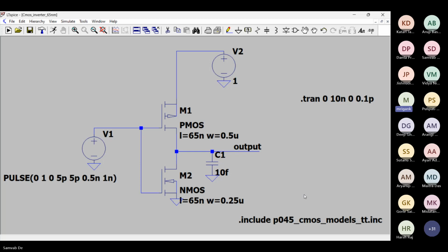All this pole zero analysis that we do, that is for analog circuits and analog signals, because they are small signal parameters, and the small signal resistance, small signal capacitances, they determine the pole. In this case, it is a large signal thing. So one thing which will change maybe is the current which was usually before spiking, like rapidly spiking and then falling, will not be that much of a spike, but it will take some time to retain and then it will fall.